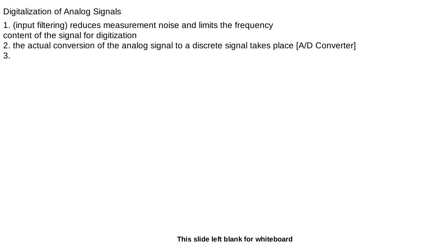And such measurement noise is often the result of disturbances from other electronic equipment, for example, from the power supply or from operational equipment such as motors and pumps. And measurement noise can also be a result of changes in the physical process variable that is being measured.